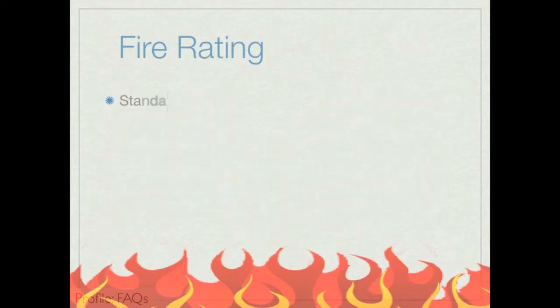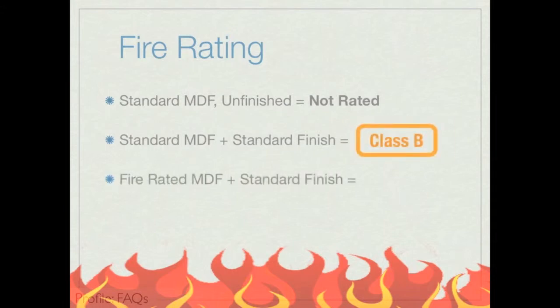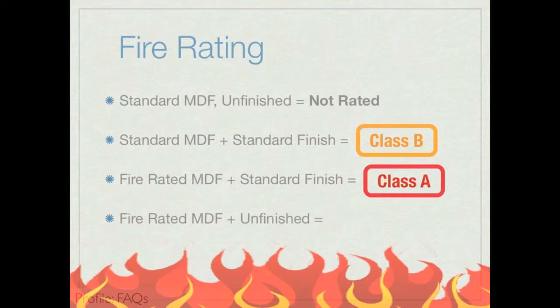First, be aware that standard MDF that is unfinished does not qualify for a fire rating. However, standard MDF with the standard finish received the Class B rating. Fire-rated MDF with the standard finish received the Class A rating. And fire-rated MDF that is unfinished also received the Class A rating. That's pretty good.